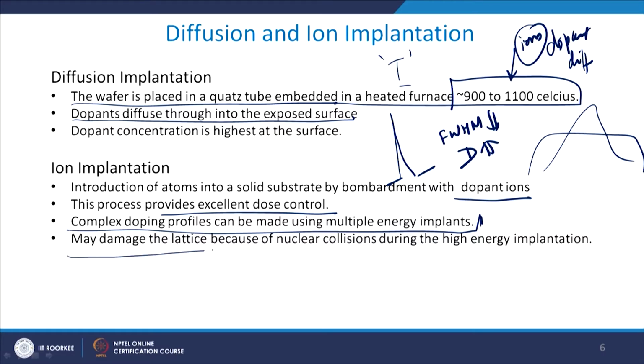But the problem with this ion implantation is that the energy is so high that you end up having maybe dislocation of the atoms through which these charged particles are passing, right, and that is a problem area which people face.